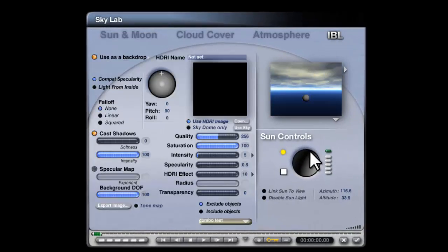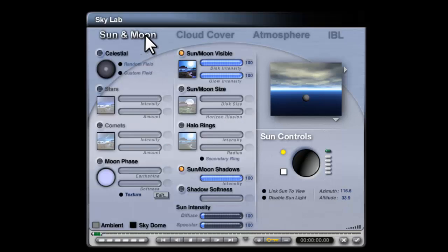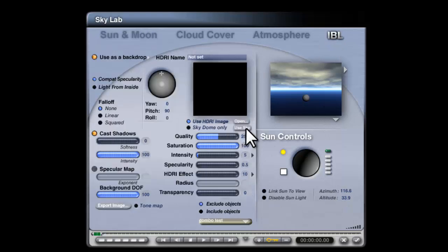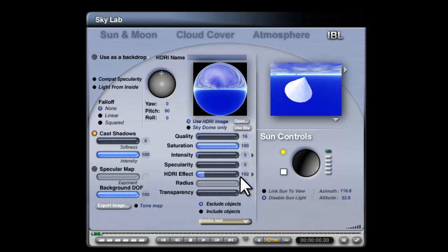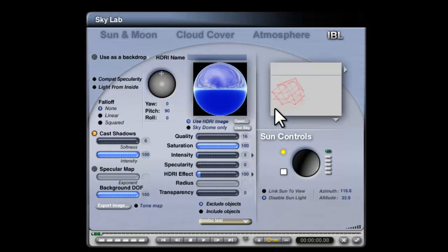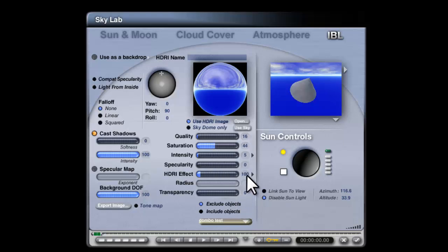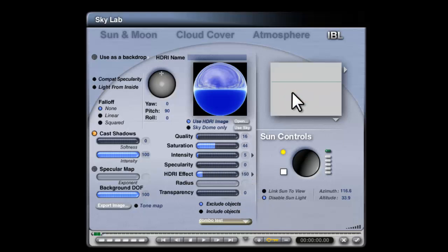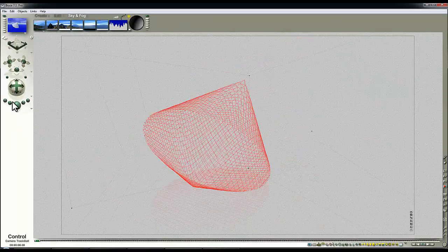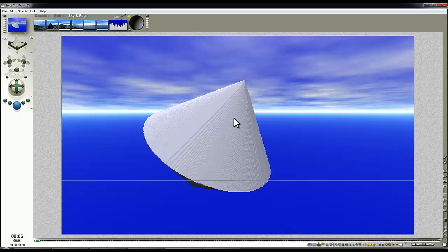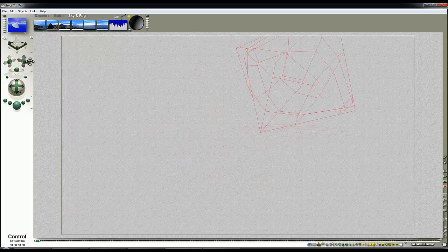So I've moved my shape into that position, and I'm going to create a quick HDRI light source so that we can light it all round. And if I remove the sun as a visible object in the sky before I use sky, then that'll mean we've just got general lighting. I'll render in scene, and then I'll lower the quality there for speed. Cut out specular response, don't need that. Put that about 100. So I can just get a general all-round lighting from this. If it's rather blue, I'll just cut the saturation down there. I'll try 150. So that's just giving me some light. So I can now use my camera to look around this object. So here we go, that's our object there, and it's lit above and below.